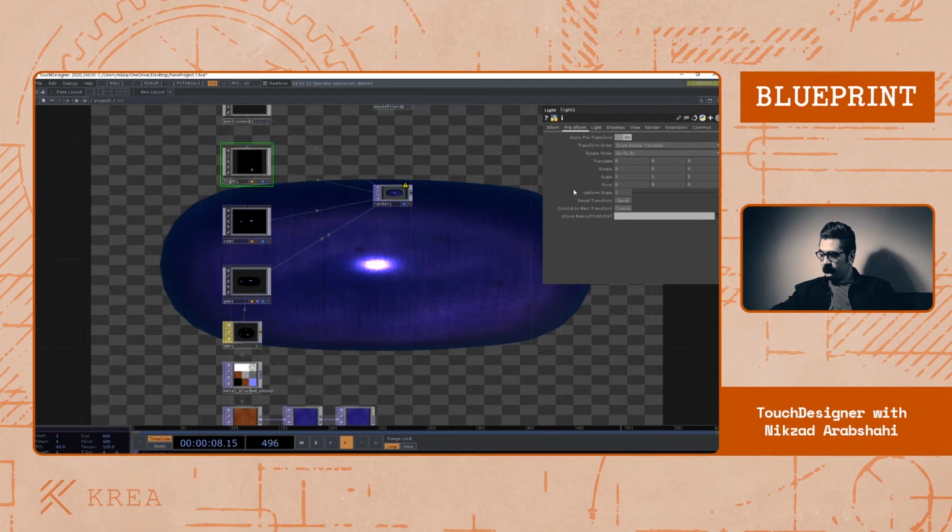Okay, now let's go to the shadow page. By default, the shadow page is off. You can just choose hard shadow or soft shadow. Let's go to the soft shadow. You can change the resolution to refine the shadow resolution, and also you can change the filter samples to make your shadow resolution much better.